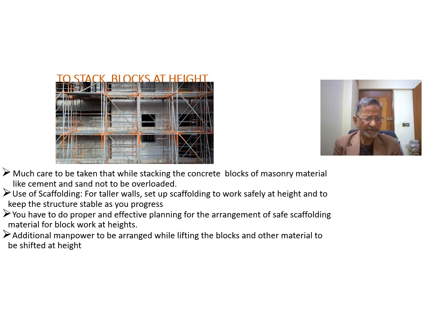So we have to take care of all the safety precautions and safety kits to be worn by all the workers. This is very, very important. Also, for lifting the material like blocks and bricks and cement, extra manpower is to be engaged so that they should smoothly shift the material to the top for the workers.